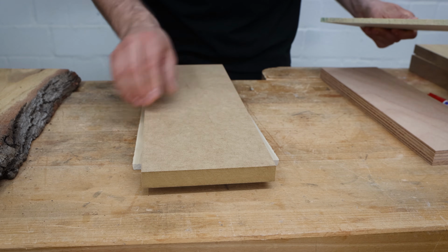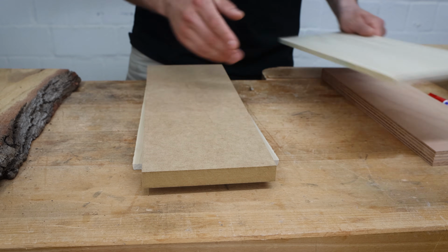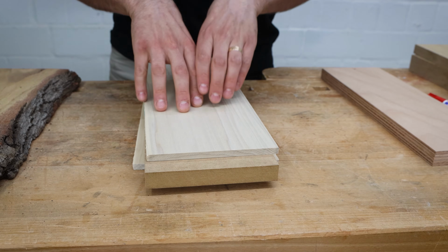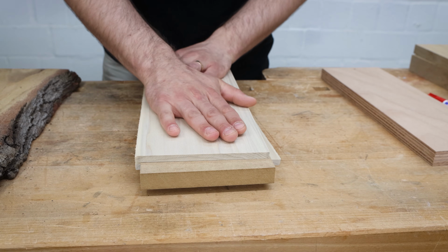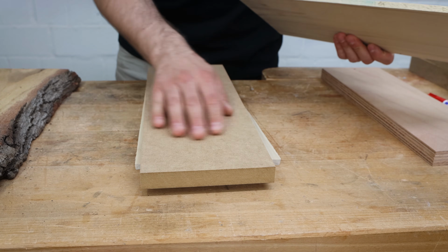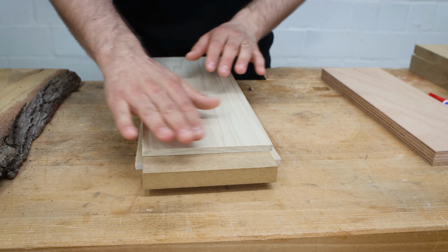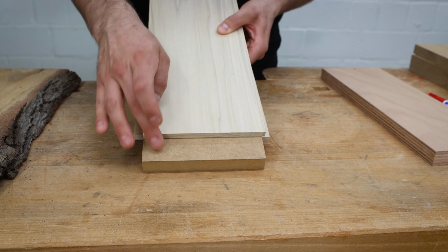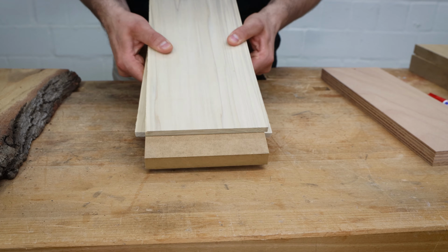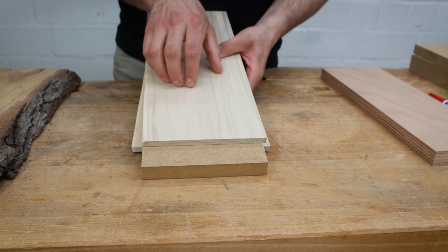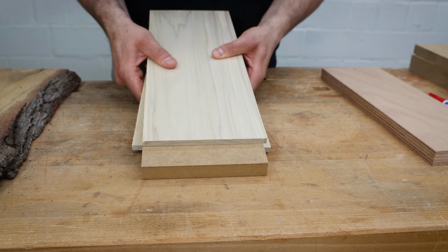Then as a center, you take a piece of MDF, and as a top, again, your veneer. You can glue these three layers together. It's important to have glue all over the surface and have a nice even pressure all over the board. Thereby the MDF is locking these two layers into place, and there will not be much expansion and contraction happening.